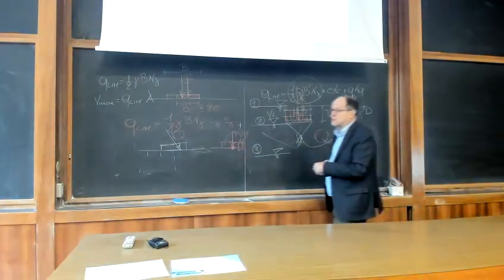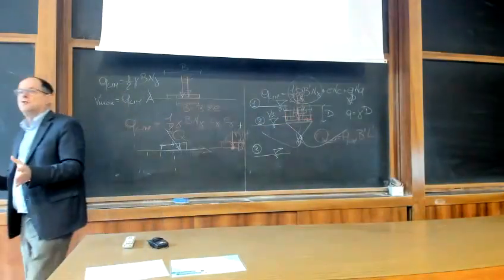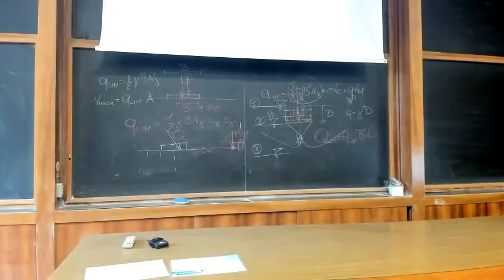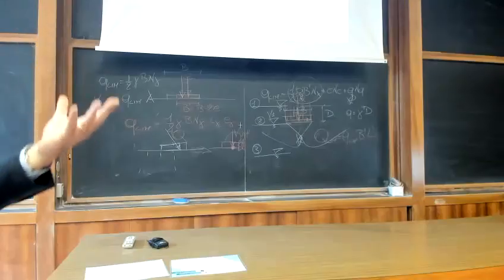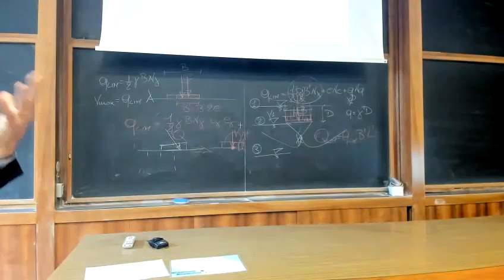Let's, for example, consider only an inclined load. So we are in the HV plane. You have your external maximum envelope, and your load combination lies in B, because you have an important vertical load, which takes you to A, and then you have a possible horizontal loading component, which takes you to B. So you are in B, and you get to failure when you touch that failure envelope. But you can touch the failure envelope in 1, in 2, in 3, in 4, whatever. Depending on what? Depending on your load path.